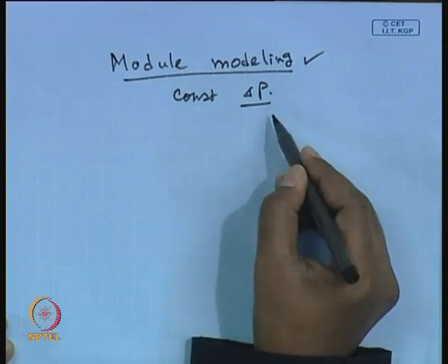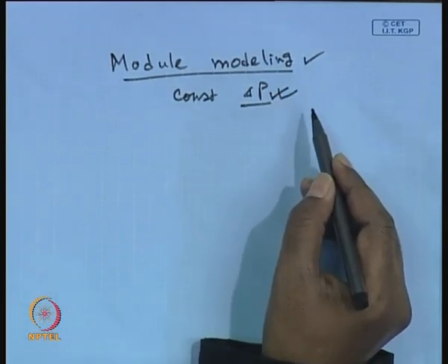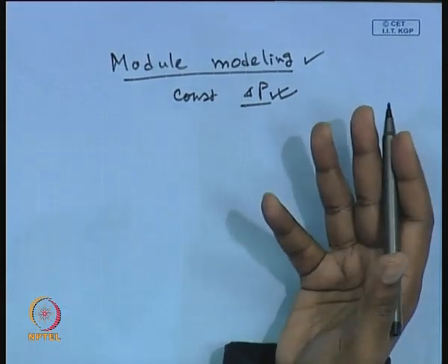But the transmembrane pressure drop can be considered constant only if we are talking about a length of, let us say, 10 centimeter or 30 centimeter, but an actual membrane module is larger in length. For example, it can be anything from 1 meter or higher. 1 meter means 3 feet already. So over the length of the module there will be a drop in delta P.